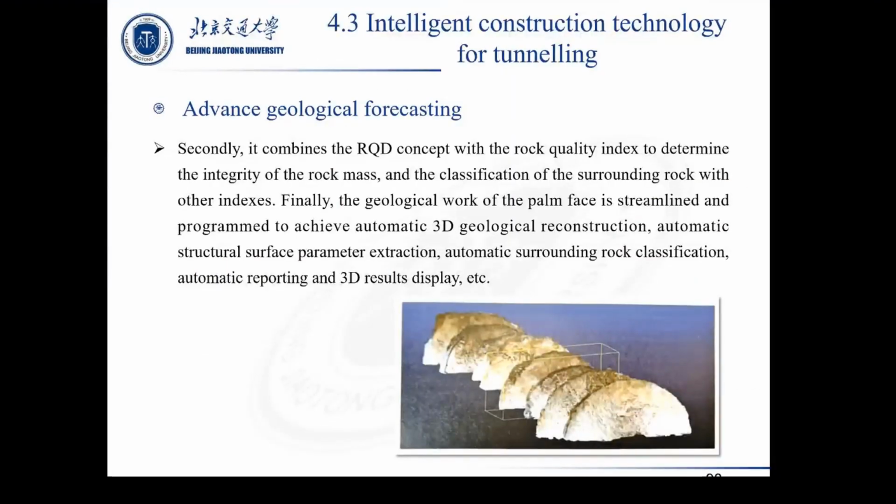Secondly, it combines the RQD concept with a rock quality index to determine the integrity of the rock mass, and the classification of the surrounding rock with other indexes.